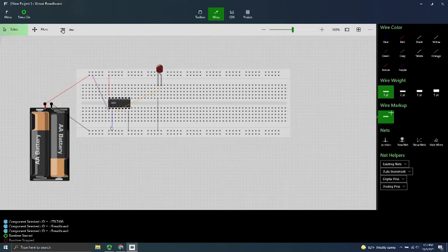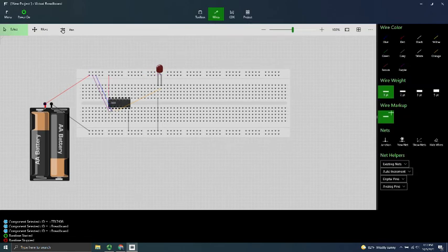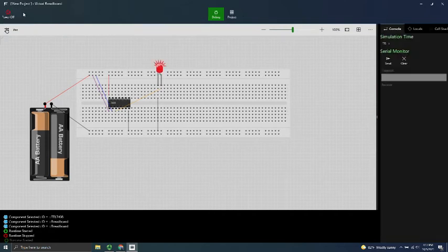Turn that off, and let's see if I can move it without having to rewire it. Let's do this. And remember, I can hook it up anywhere here, but I'm just going to do it right over here to keep it close. Okay. And let's do that. So now both of these inputs are with the positive side of the battery, and so that means that AND gate should be active and should output that 5 volts to the LED and go to ground and turn on. Let's see if we did everything correctly. And the LED is on. Fantastic.